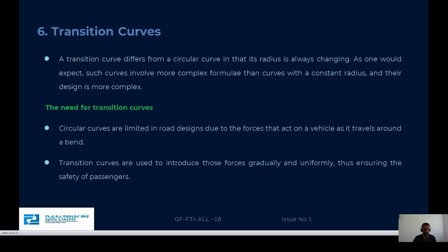A very important part is the transition curves. The transition curve is different from the circular curve, because its radius is always changing. As previously discussed, the circular curve is provided between tangents, while the transition curve is provided between the circle and the tangents.